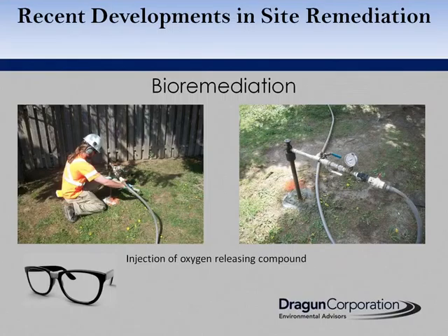So this brings us into our next topic, which is bioremediation, more specifically in situ bioremediation. This is a technique that is commonly used either in low concentration groundwater plumes or at the tail end of a remediation program as a polishing technique to finish off a remediation program.